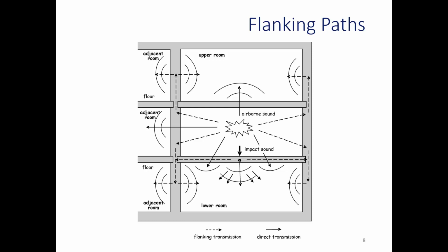You can have very different results for airborne and impact. Like, say you put a 6-inch concrete slab there, you get pretty good STC from that, but your IIC is going to be terrible. You'll get 50 or more with the 6-inch concrete slab on the airborne side, and more like less than 25 on the impact side, and vice versa.